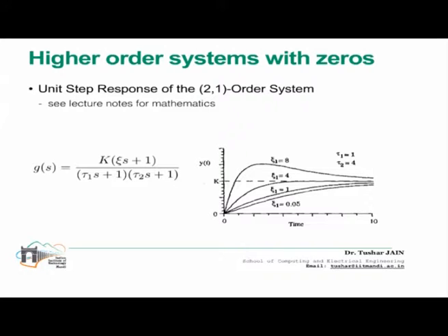This would be my tau 1, the pole. Okay, now by this case 4, where xi 1 is less than 0, I would have a zero somewhere. You move the zero to the right hand side, which is very problematic, because what we have seen, whatever moves to the right hand side will create problems, in the sense your system might become unstable.